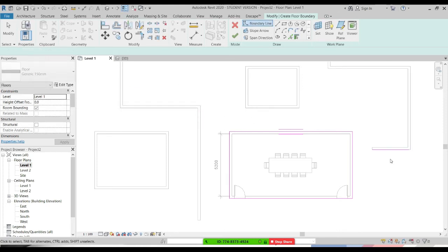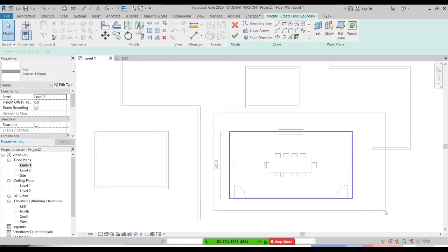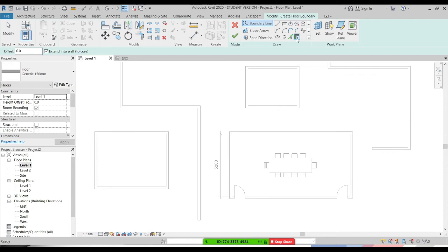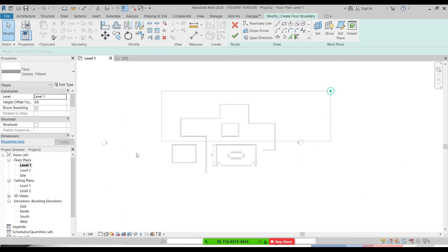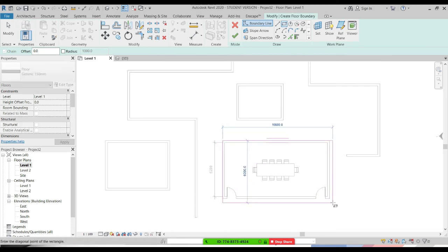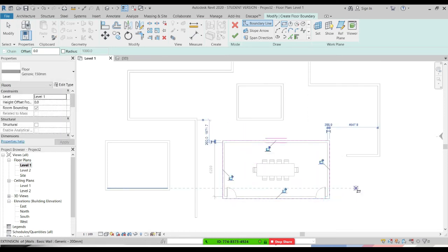Can you show again the right way? Yes. So the right way of this is to pick walls and then make sure that the walls you're picking are in a closed loop. Otherwise, you'll end up with an open sketch. Another way to do it, if you press escape, just press escape twice, you can select everything by window, delete, to make sure that nothing is there. And go back to the same, select rectangle, for example, and create a rectangle from that corner to the other. That's another way to do it.